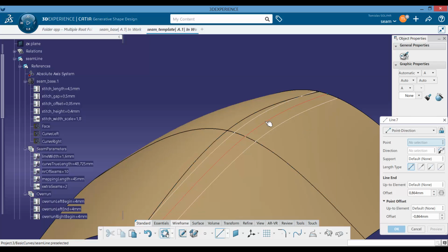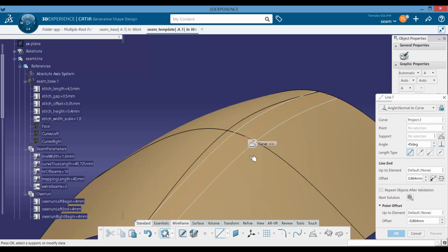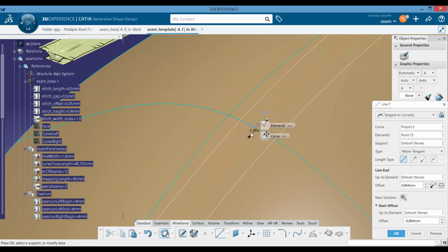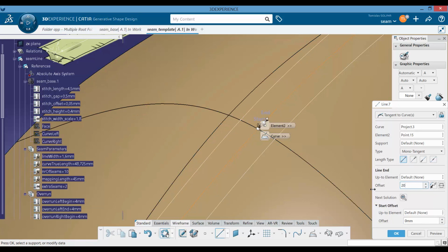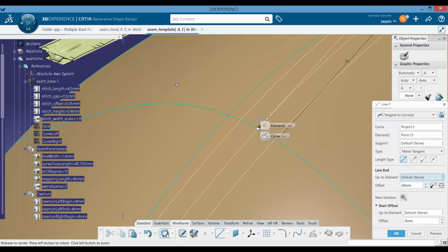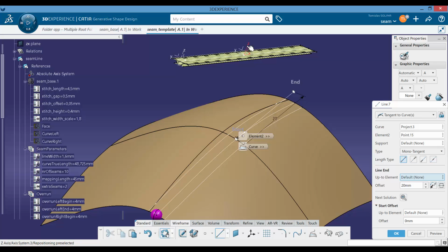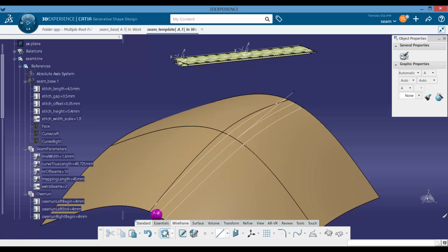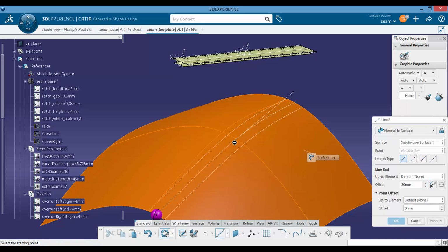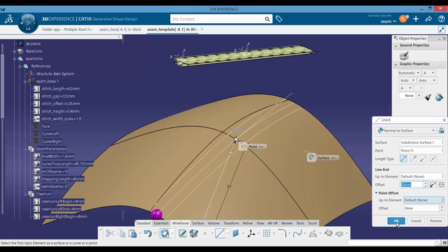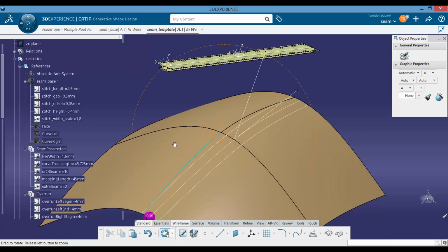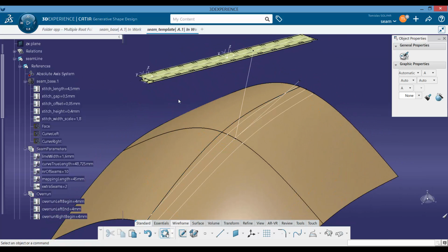So we'll have the line which is tangent to this line, to this curve, starts on 0 and ends in, let's say, 20 millimeter. This dimension itself doesn't matter, it's only here to define where the axis will be. Other direction that we know and always know where it is of course the normal. Flip so that it looks similar to axis. It won't make any difference because the orientation will logically stay the same.